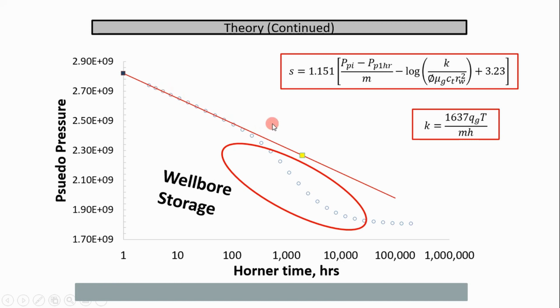line portion. And then this point represents your well flowing condition at 1 hour on this line after you shut it in. So you have your time produced, you shut it in, you add an hour, and that's your pseudo pressure at a well flowing time of 1 hour, and this is your average reservoir pressure.